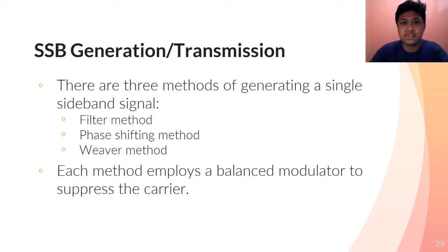The transmitters used for a single sideband suppressed carrier and reduced carrier transmission are identical, except the reinserted carrier transmitters have an additional circuit that adds a low amplitude carrier to the single sideband waveform after the suppressed carrier modulation has been performed and one of the sidebands has been removed. The reinserted carrier is called the pilot carrier.